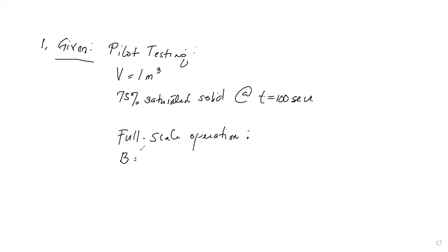Now, you have to be very careful. It says here 500 kilogram of the inert solid containing, as before, 28% by mass of water-soluble component. So it could be easily confused that your 500 kilogram of inert solid is just B. But actually, this 500 kilogram of inert solid that is being referred to in here is the one that contains 28% by mass your water-soluble component, since water was used in dissolving the solute. And that's your solute A in this case.